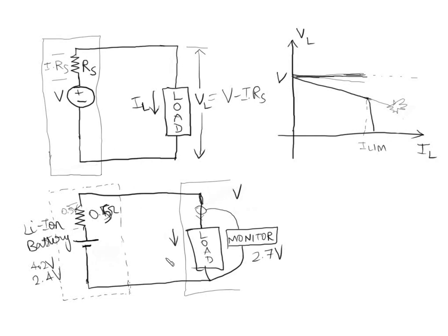An even more annoying situation can be that, let's say you are using your phone for some power intensive application, like watching a YouTube video. The current drawn by the phone would increase quite a bit. Let's say it increases to 2 amps. Now if we are drawing 2 amps through a 0.5 ohm intrinsic impedance, you're going to drop 1 volt across this directly. So even if the internal battery chemistry voltage is pretty high at 3.7 volts, the actual voltage delivered by the battery will be only 2.7.